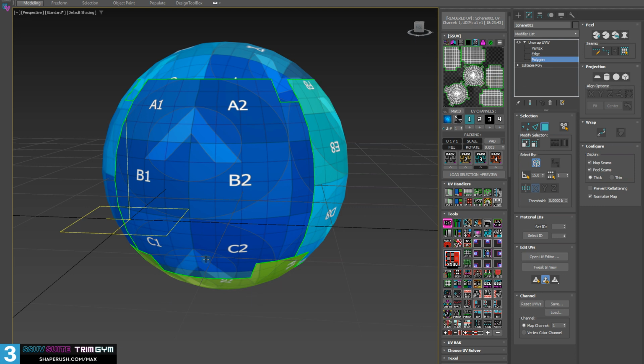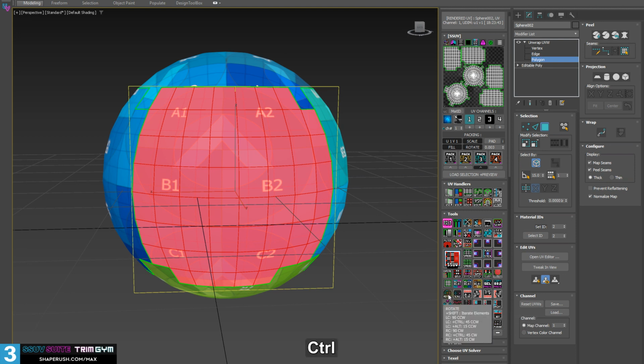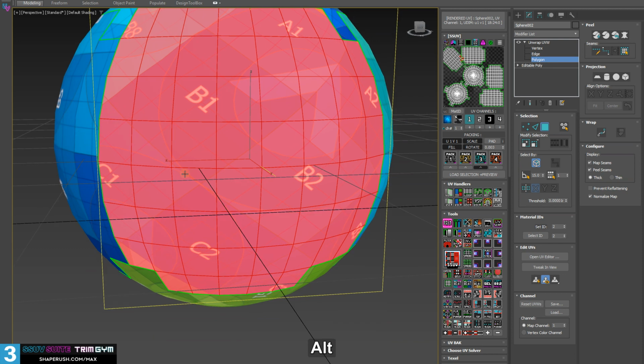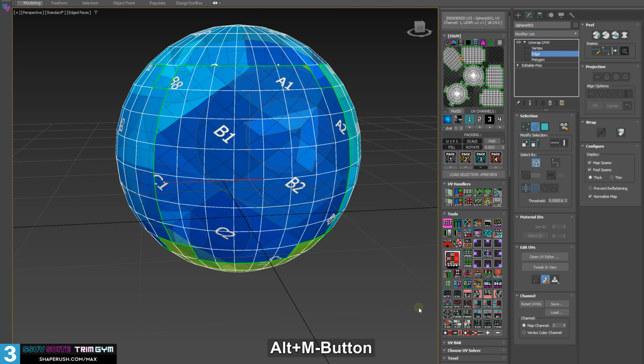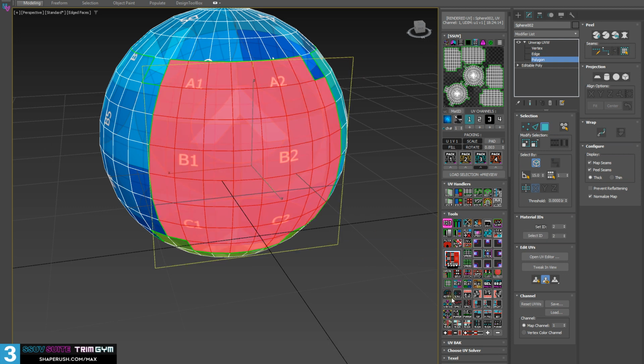That's your straighten. And if you end up with, let me just show you this real quick, anything that's at an angle. So this is at a 45-degree angle. To straighten that, go into edge mode, select an edge on that element, and then you can click this align button. Not these other align buttons, but this one specifically. And that will take the closest 90 degrees, I believe I set it to. So if it's going to go vertical or horizontal, and then you're set. If you need to continue rotating it, select the element and use the rotate feature.